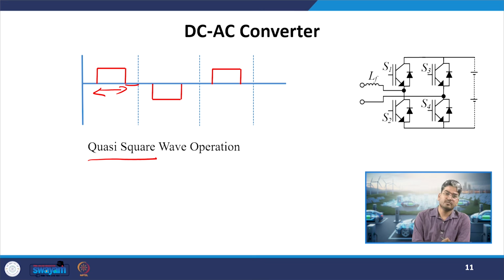So, I have got voltage regulation, or if my DC link voltage is fixed, then the AC voltage can be changed. Okay. What will be the limitation of this one? Still the THD will be higher compared to our high frequency operation, because the dominant harmonic will still be at the lower end side. And we have seen that if the dominant harmonic is at a lower end frequency, it will have a major effect on the load.